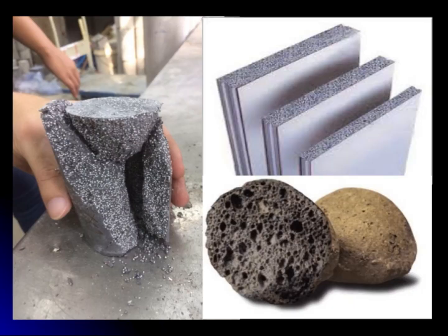The lightweight concrete is typically produced by using lightweight aggregates such as expanded clay and EPS foam bead or air foaming agents as shown in the picture. It helps reduce overall weight of buildings and is suitable for applications where weight reduction is critical. However, the strength of lightweight concrete is generally lower than that of normal weight concrete due to its higher void content.